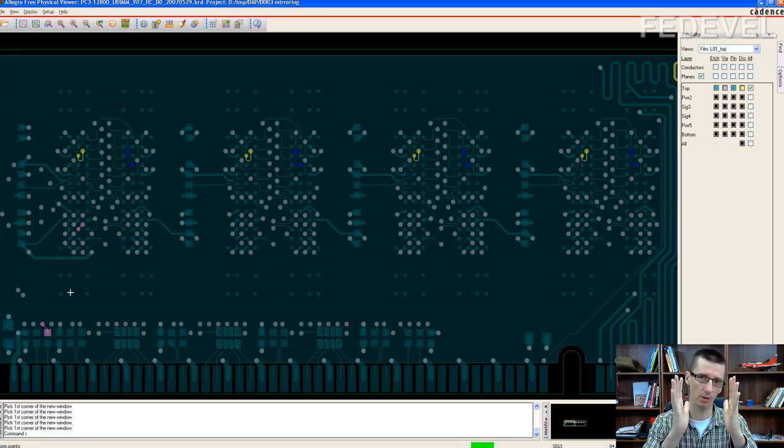The bottom memory chip is connected to different data lines. In this example, they connect the top and the bottom memory chip to the same data signal. And because it is a high-speed interface, it is very important how you make the layout for this kind of connection.